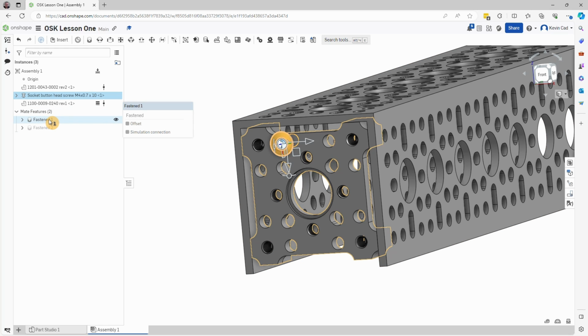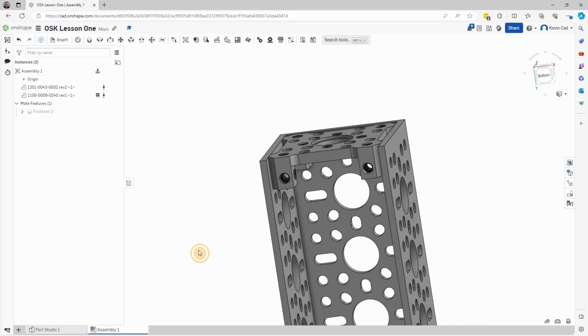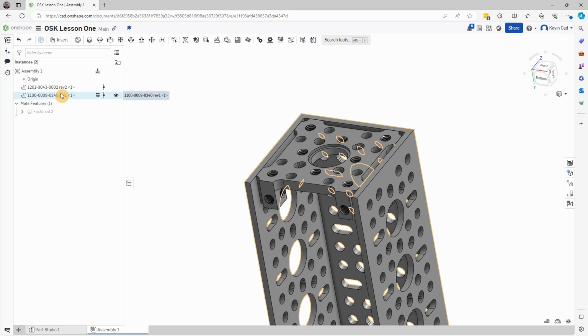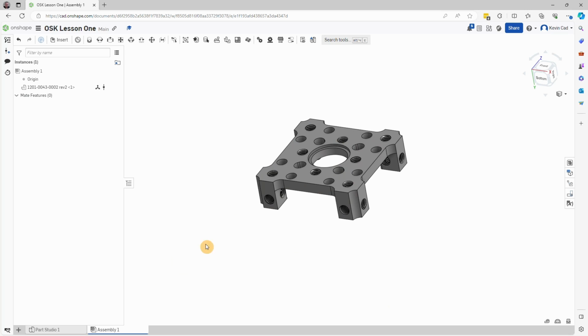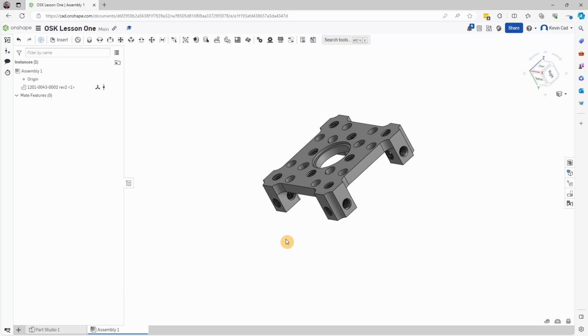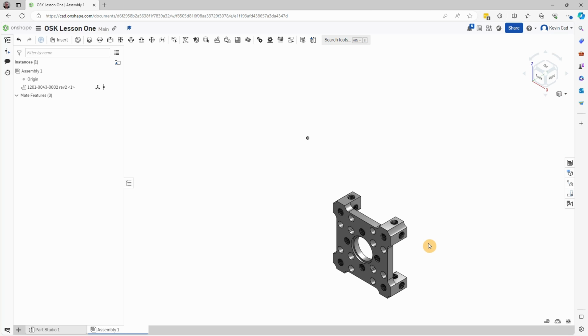See it here? In order to get ready for the next section, in addition to removing the screw, we're going to delete that channel there, and we are going to end up just back to our original part. Now what I'd like you to do is to use the view cube, the camera and rendering options. I'd like you to put us in isometric mode and see how our part, which is no longer fixed, by the way, if yours is fixed, turn the fix off.